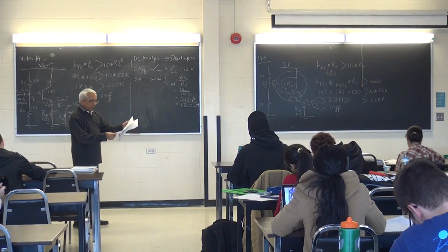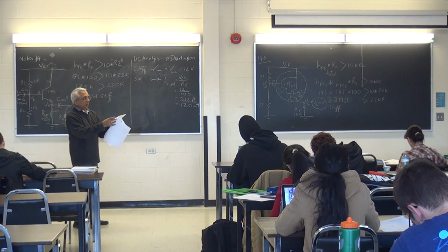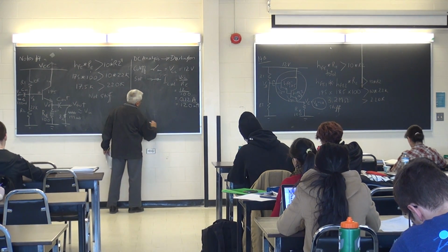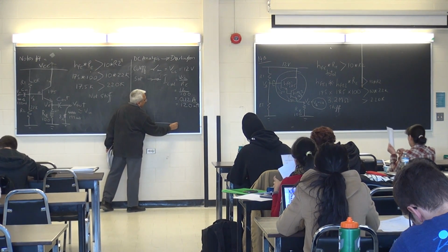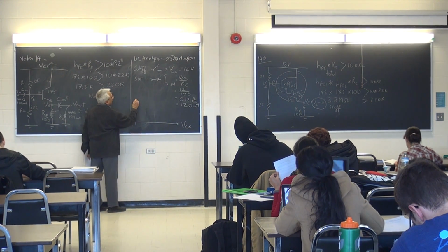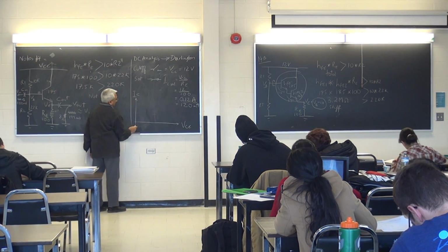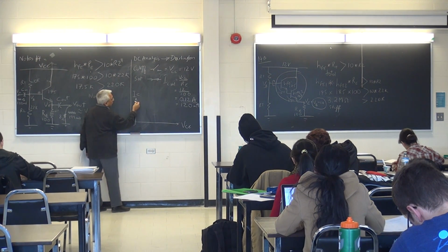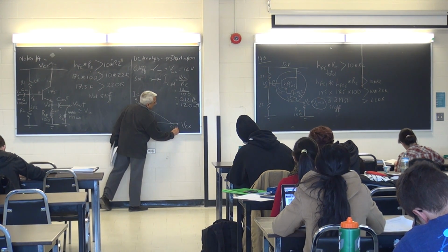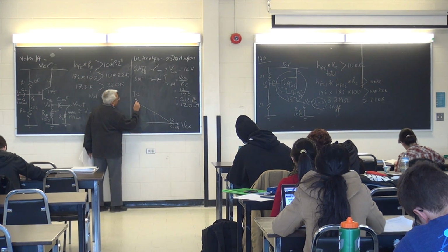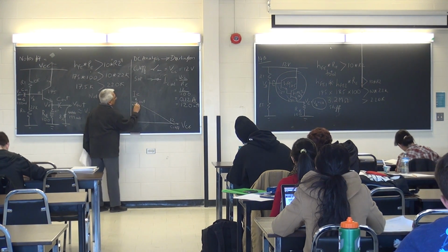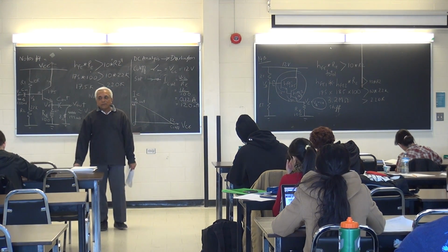So can we now go to page 2 of notes 14B and draw my load line? X-axis is what? VCE. Y-axis is what? IC. Where they two intersect, 0. Draw your load line. Cut off here, how much? 12. Saturation is how much? 120 milliamps. Okay, so there's my load line for this circuit.